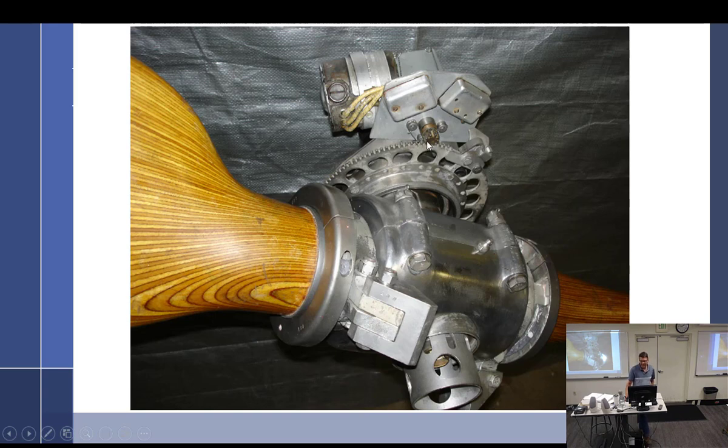But this had an option for the pilot. Either they had an electric switch, if you had the really fancy one, or a little crank. Kind of like, well, you guys wouldn't know, but back in the olden days, this is how we got the window to go down. A little crank, or the electric motor, would turn this pinion gear against this gear right here, and this is all spinning around except the gears aren't.